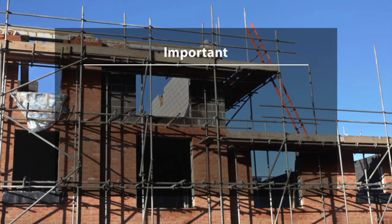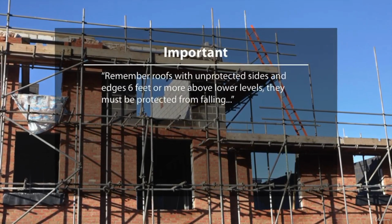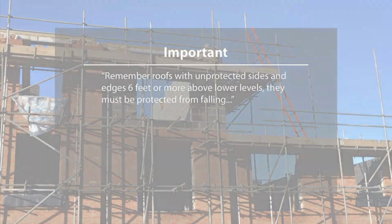If employees are working on roofs with unprotected sides and edges 6 feet or more above lower levels, they must be protected from falling by use of guardrail systems, safety net systems, PFAS, or a combination of a warning line system and guardrail system, warning line system and safety net system, and safety monitoring system.